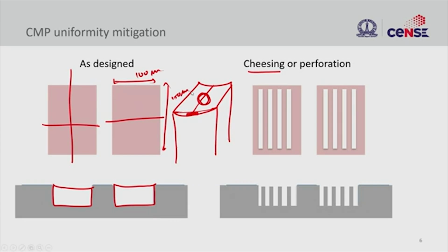So where you will see this dishing, what we do is, instead of using this flat open area, you can segment this, right? Instead of having a fully open trench, you make this segmented trench, but they are all connected, right? So electrically they are connected. You see here, this allows you to do the electrical connection. It's not just an isolated feature.